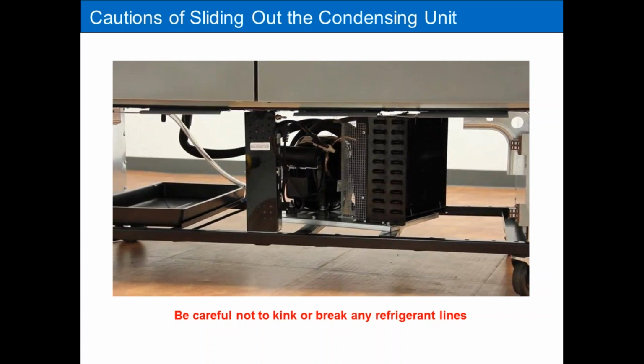The next day they called up and said the cooler stopped working that night. Unfortunately, I couldn't get there until the following day, so it was 2 days. The unit was down, and it had dumped all the refrigerant out, and the compressor failed because it was an older compressor running without any refrigerant for 2 days. They did not unplug it, and the compressor failed. So I had to change the compressor and fix the leak, which maybe could have been avoided by how I pushed it back in.